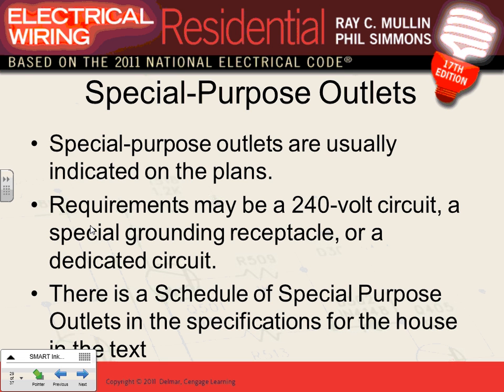There are other outlets that go 20 amp, 240; 30 amp, 240; 40 amp, 240; 50 amp, 240. These are special outlets. We'll talk about them. Notoriously famous is 30 amp for your electric dryer, and 40 or 50 amps for the range. These are the two you can use in dwelling units: the dryer and the range, 30 and 40 amp, 240 receptacles.